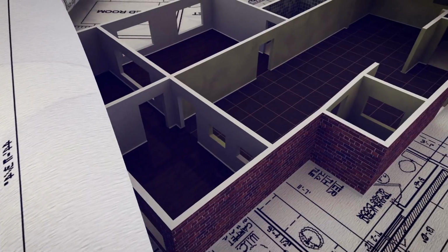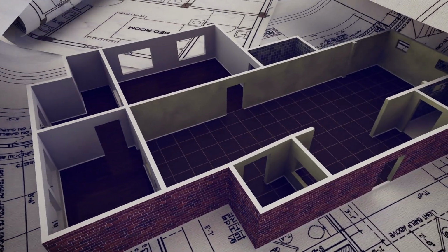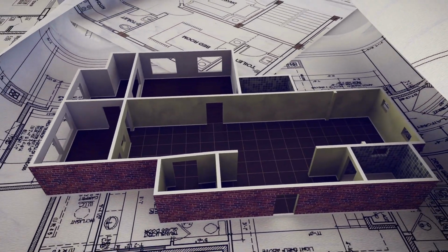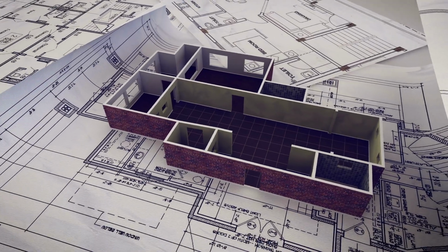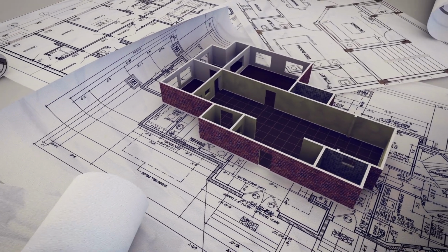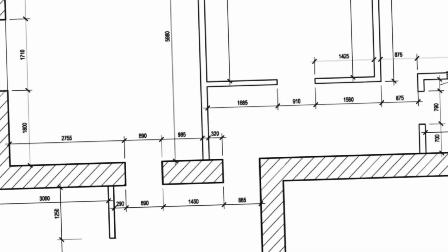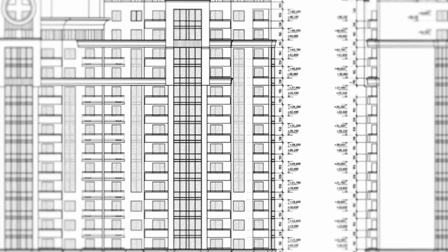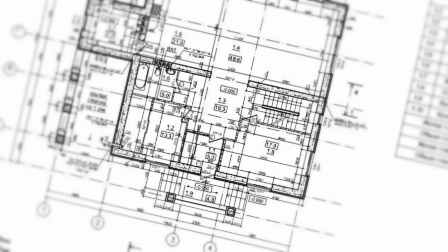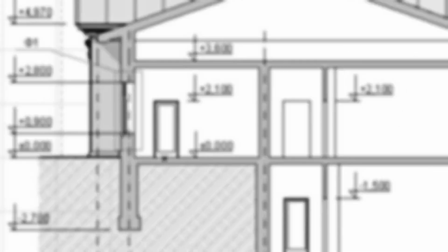Unlike design drawings, which are necessary to show the overall intention of a project before it begins, shop drawings leave nothing to the imagination, or at least they shouldn't. Shop drawings are the real deal. These are drawings, which are often produced and stamped by a professional engineer as well, that are the official drawings in terms of what is actually being constructed.